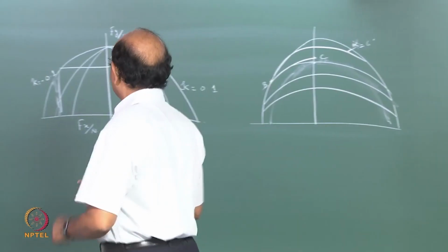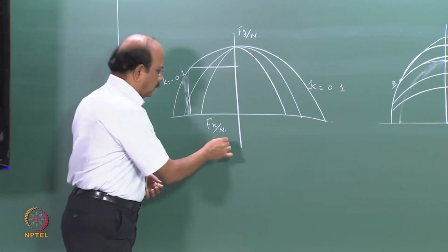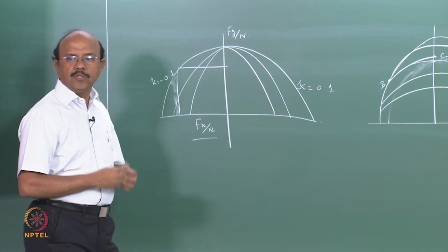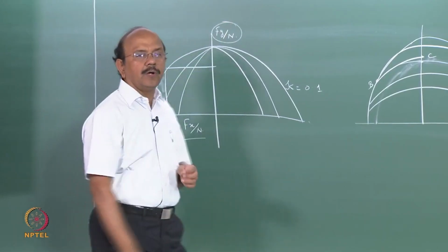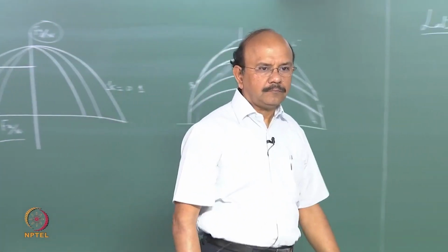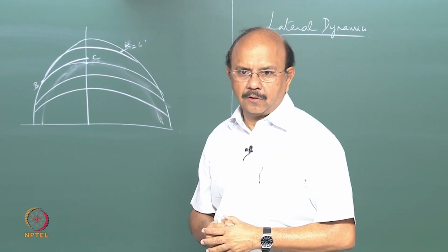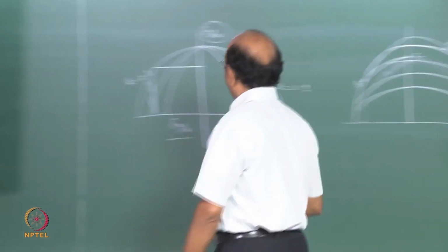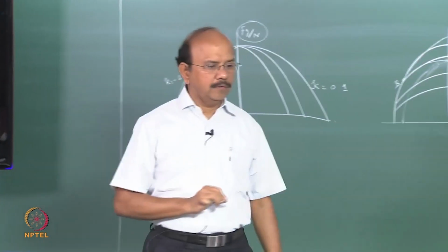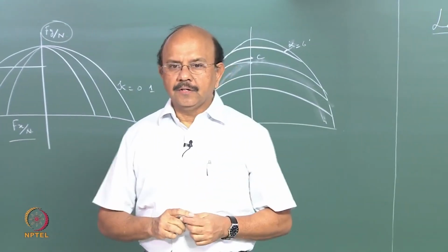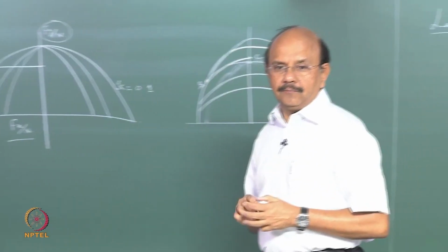Okay, when you apply the brake, actually, what are you doing? You are getting both the longitudinal forces. You require longitudinal forces for braking, as well as due to cornering, you also require a lateral force. Assume that you are at the edge of the friction circle or ellipse, as you can call it. Or in other words, you are, say, at this position. Let's say that you are at that position. In other words, you are making use of all the friction that's available, right?